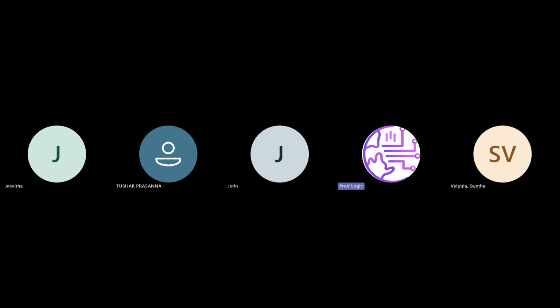And also we have another limitation in Verilog HDL: while doing randomization, if you are doing a 3-bit randomization, within 3 bits it will generate multiple repeated values. I have shown you the example also, repeating several times. But that does not happen in SystemVerilog, because in SystemVerilog we have two types, rand and randc.